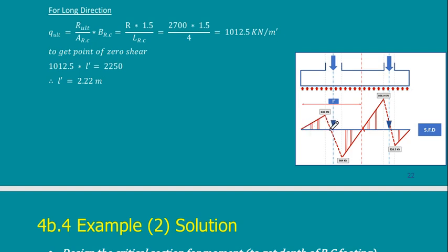And here there is a cantilever, and here there is another cantilever. I can calculate the moment here and the moment there of the cantilever. But what I don't know is the maximum moment in between these two, in this span, because this beam is actually resting on this column and resting on this column, and the load is the reaction coming from the soil. So it is as if you have an inverted beam. This is the support of the beam, here the support of the beam, and the load is here, and I need to draw the bending moment.